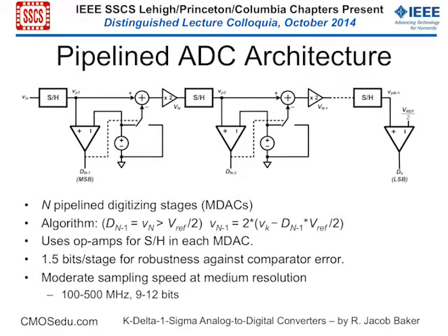So historically, this has been a really popular architecture because it doesn't take a lot of layout area. I'll put a few slides up here on correction. It's possible to do corrections to get around the errors in the pipeline ADC, and you can do things with the multiply by 2 stage, like correlated double sampling, removing the offset and low frequency noise. The issue nowadays with using this topology for real high speeds is that if you've got transistors with an open circuit gain of 5, you can't really get the needed gain here to be reasonably close to 2 without significant corrections.